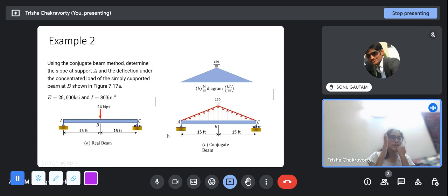And when we come from the left side, a clockwise moment is positive, so that is negative. So the contribution of this support reaction will be negative, and we are coming from one side. Now we are not going to consider the C, of course. We take a section at B. We are trying to find out the bending moment at B, so we are coming from the left side. You can also come from the right side, you will get the same answer.